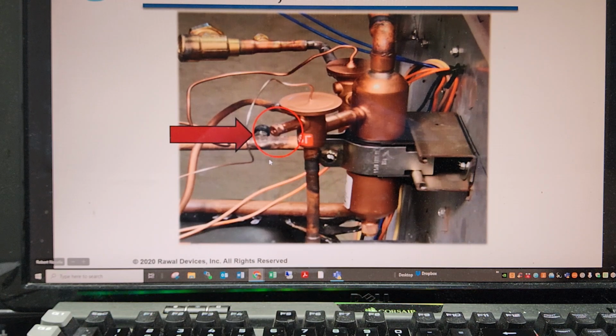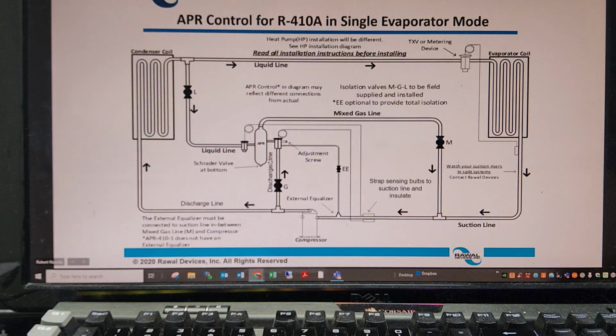That's just meant to protect your compressor from overheating. It's maintaining that 20-degree superheat or 65-degree suction line temperature. That's all it's really doing. But it's really hard to get back into adjustment if it gets moved out. I'm sure you have a sticker on there, right? We got a sticker on there. Very good, thank you. Does it use the word never? Yeah, never adjust that. If you have any questions, just give us a call. Got it, thank you.